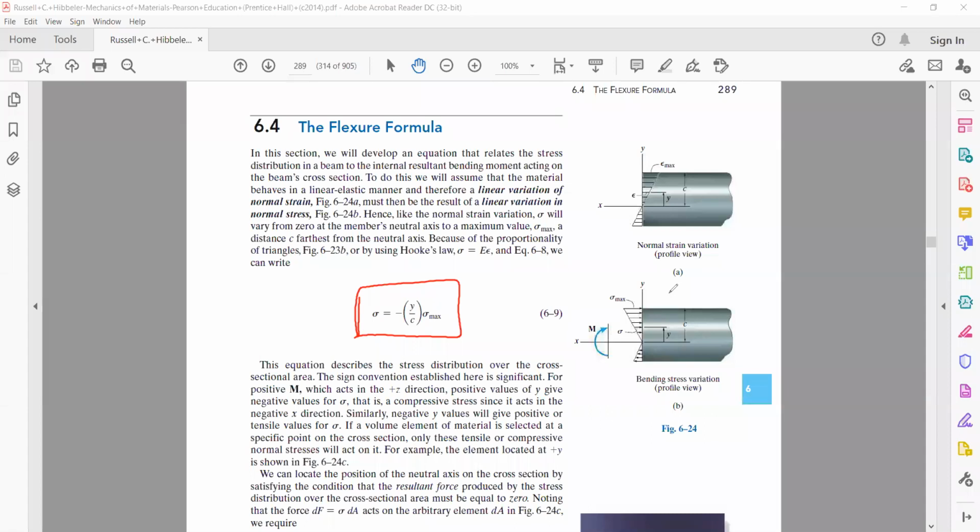So we were saying that as the beam is loaded, you will have a section out here, because what has been done is we have taken a small section out of this beam, and then we are doing the force balance. But essentially, this portion of the beam will be in contact with this portion of the beam, right? And these forces are created on this section in response to the external deforming force by the other section of the beam.